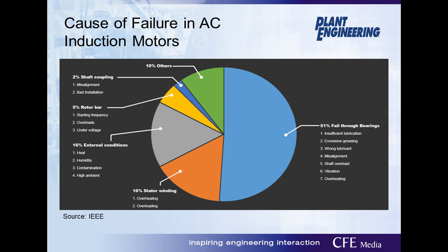We will start by looking at causes of failure in AC induction motors. We know that electric motors are electromechanical devices housing both electrical and mechanical components. For me, as someone with an electrical background, I'm happy to report the leading cause of failure in electric motors are the mechanical bearings. Really, outside of the structural design, the bearings are the only mechanical element of the motor, so all you mechanical folks need to step it up.